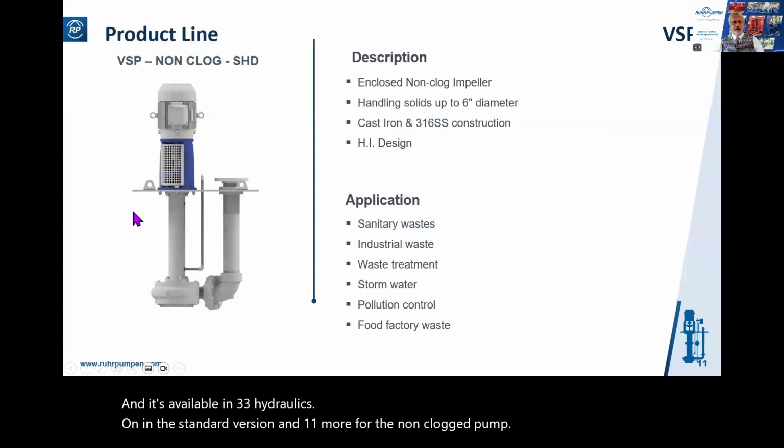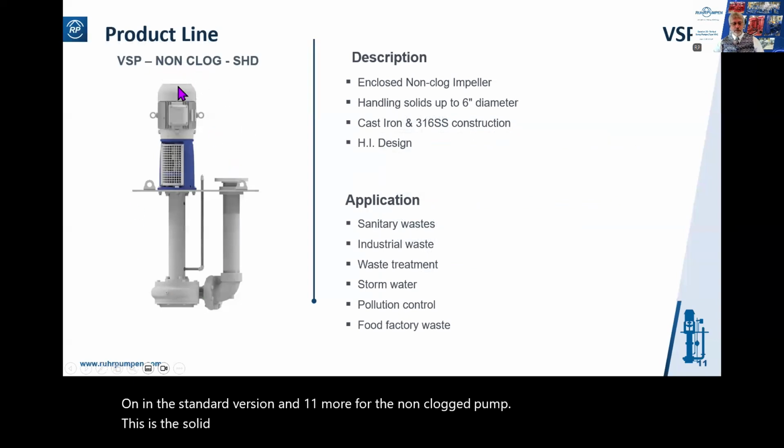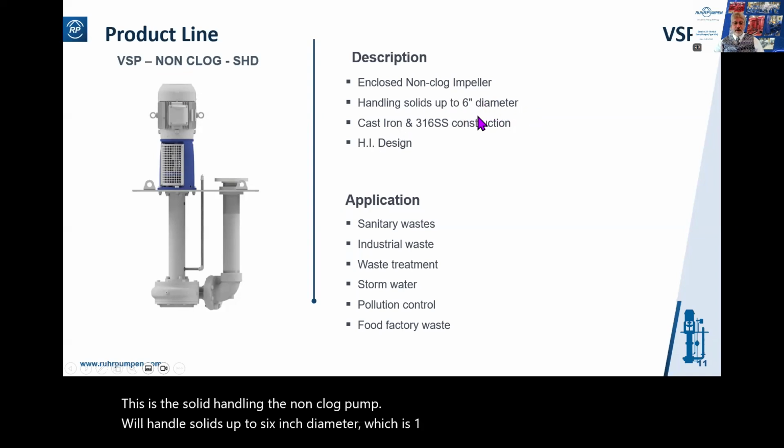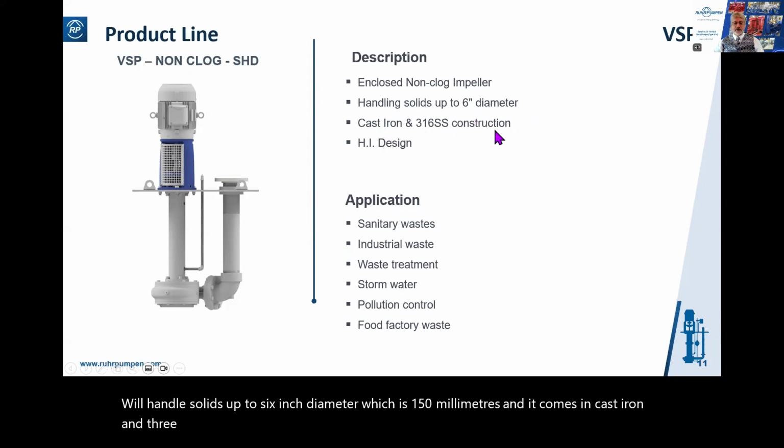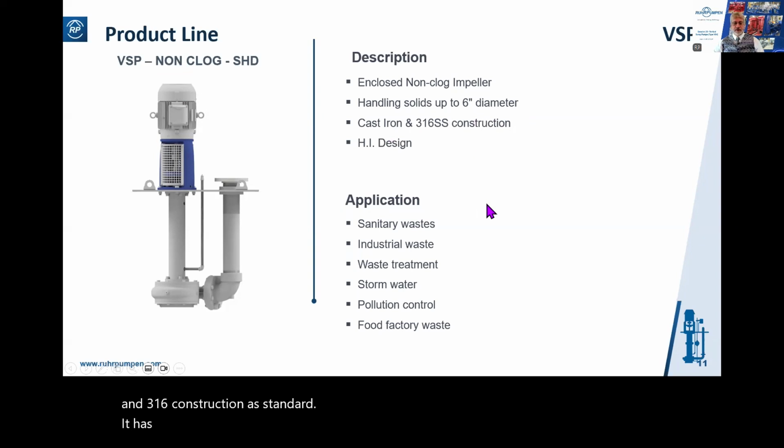And this is the solids handling, the non-clog pump. It will handle solids up to 6-inch diameter, which is 150 millimeters, and it comes in cast iron and 316 construction as standard. It has 11 hydraulic sizes.